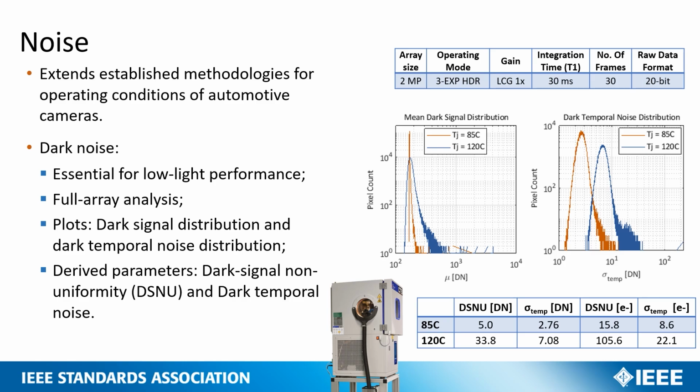So what the standard defines are many different metrics for the dark noise. As the dark statistics are quite important for designing and for checking your sensor, there are different metrics defined for that. What is interesting is that it is important to perform dark signal measurements over different temperatures. So that's where, for example, our IQ climate chamber is of interest, because it's a setup where you can easily change the intensities or the temperatures and then measure the performance of the imager over temperature.